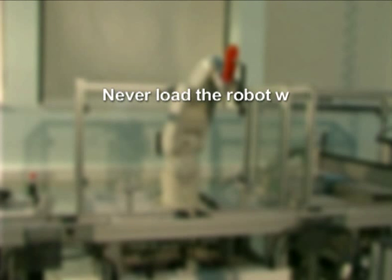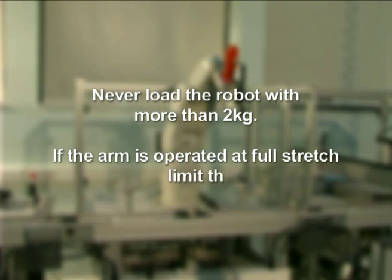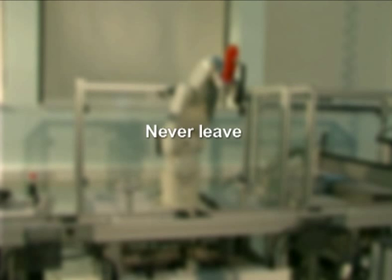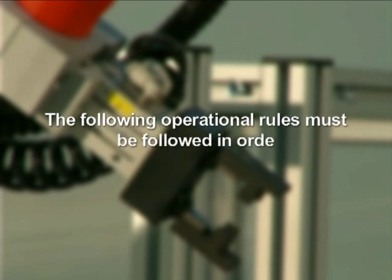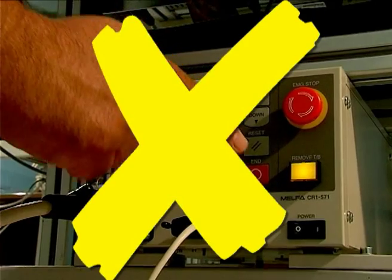Never load the robot with more than 2 kilograms. If the arm is operated at full stretch, limit the maximum load to 0.5 of a kilogram. Never leave the robot unattended when it is powered up. The following operational rules must be followed in order to prevent damage to the robot. Do not switch off the controller power while the robot has power on the servo.